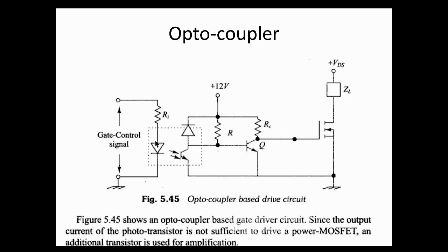Your input current should be so much. So what resistor would you select? You're getting 5 volts, let's say, from your microcontroller's output. You don't want the current flowing through your LED to exceed the rating provided by the manufacturer.